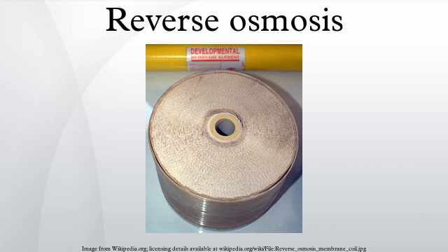The deposits inside or outside the boiler tubes may result in underperformance of the boiler, bringing down its efficiency and resulting in poor steam production, hence poor power production at the turbine. It is also used to clean effluent and brackish groundwater. The effluent in larger volumes should be treated in an effluent treatment plant first, and then the clear effluent is subjected to reverse osmosis system. Treatment cost is reduced significantly and membrane life of the reverse osmosis system is increased.